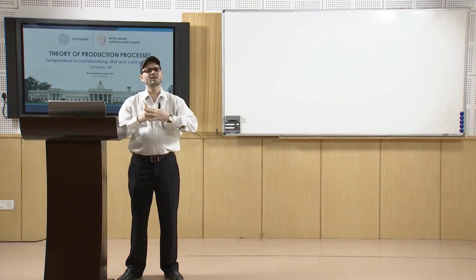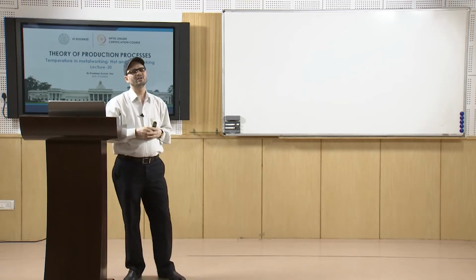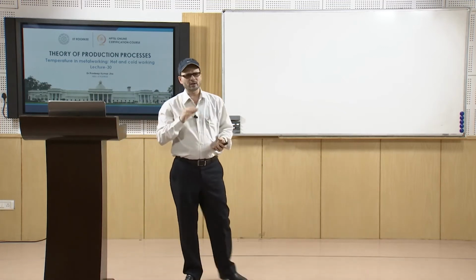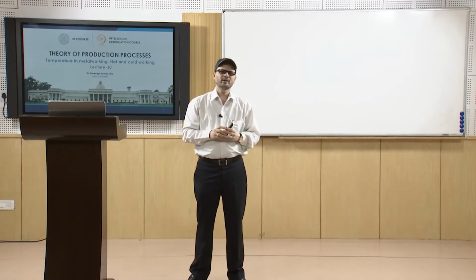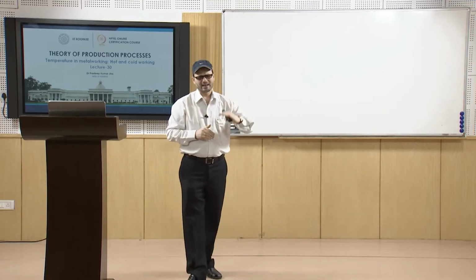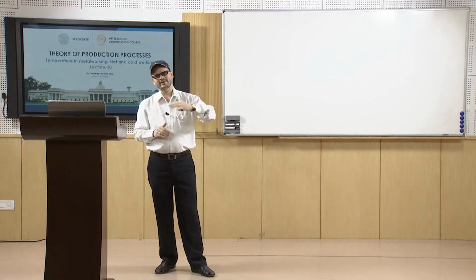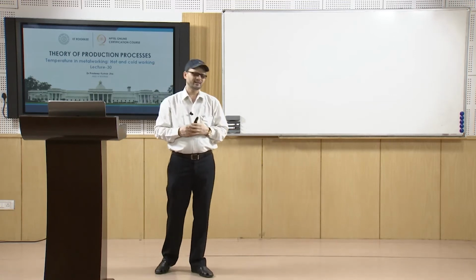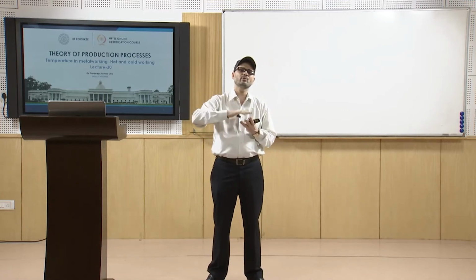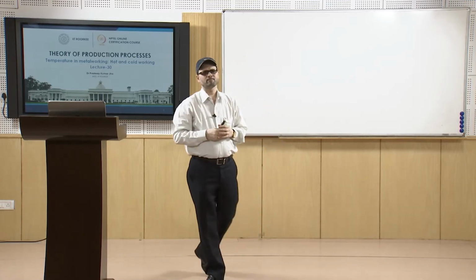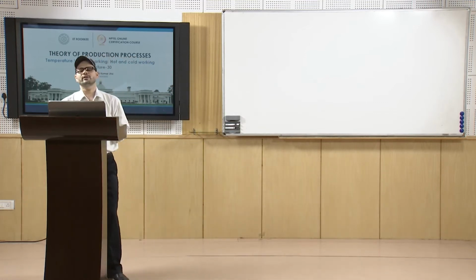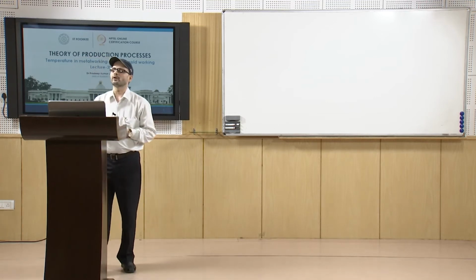Okay. So, normally you have a constant value of flow stress, and its value is quite small as compared to cold working, because in cold working, as we do the straining, the flow stress goes on increasing. As we go on doing the reduction, with the degree of reduction the flow stress value will be more and more. So, that is the difference between hot working and cold working.